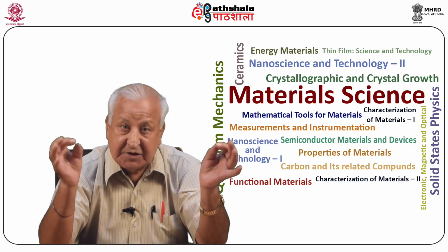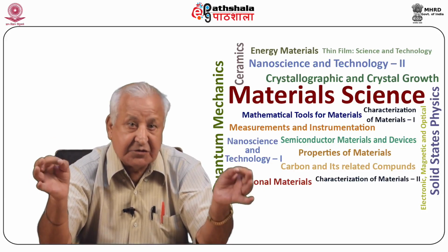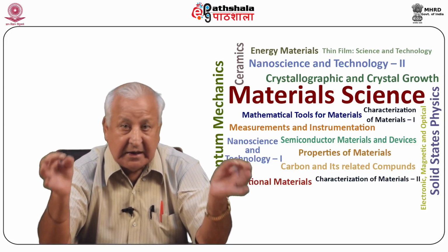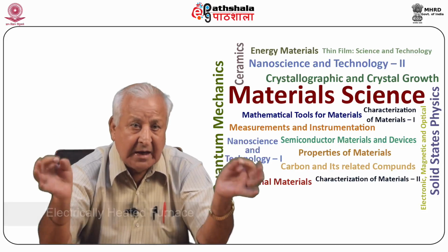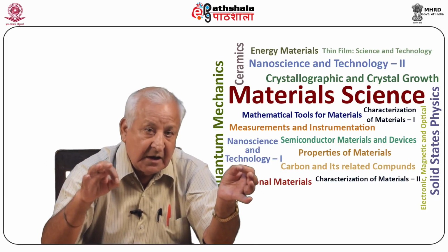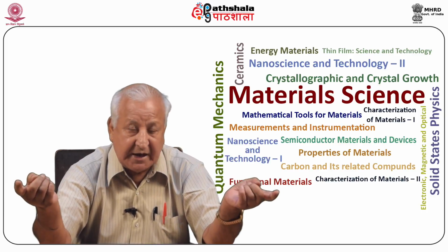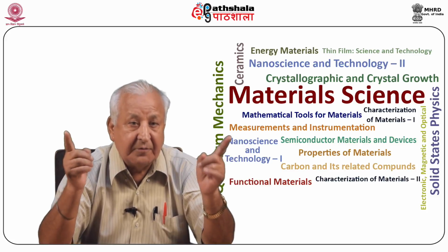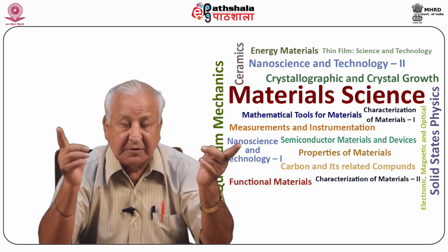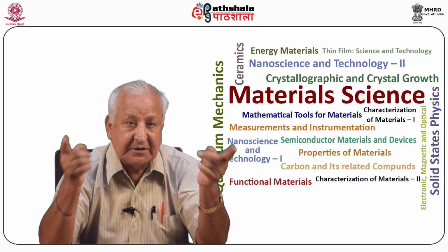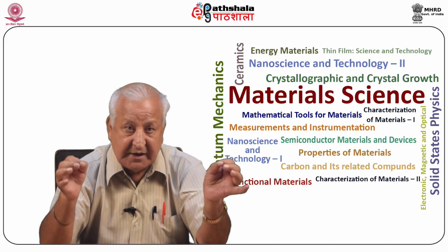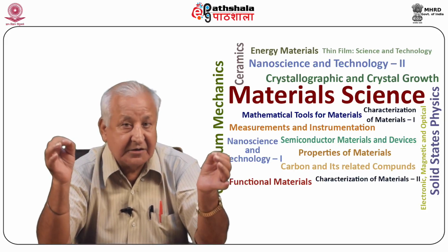The crucible, charged with the flux and constituent chemicals, is placed on a pedestal as shown in the figure in an electrically heated furnace. The pedestal is rotated 30 turns in one direction and 30 turns in the opposite direction to obtain uniform mixture of the molten contents of the crucible. The temperature of the furnace is raised to 1300 degrees centigrade. At this temperature, the aluminum oxide and chromium oxide get dissolved.